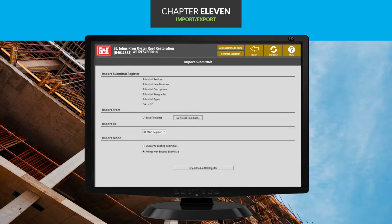We're going to select the radio button, Merge with Existing Submittals, and add the new submittal register without removing existing items. The only drawback to this option is that we may see duplicate items. In this case, RMS will automatically increment the item numbers.